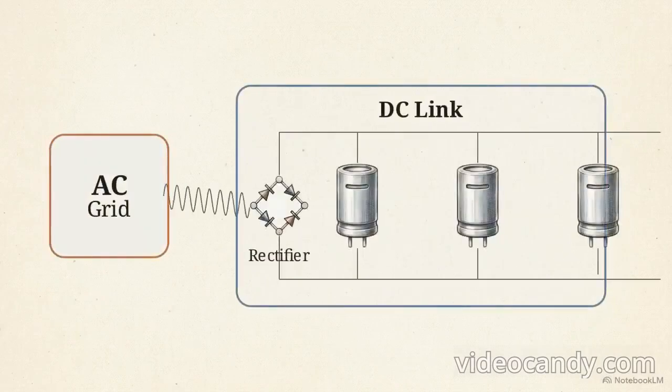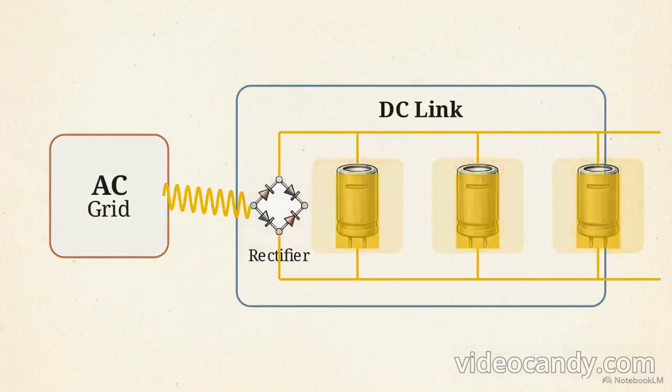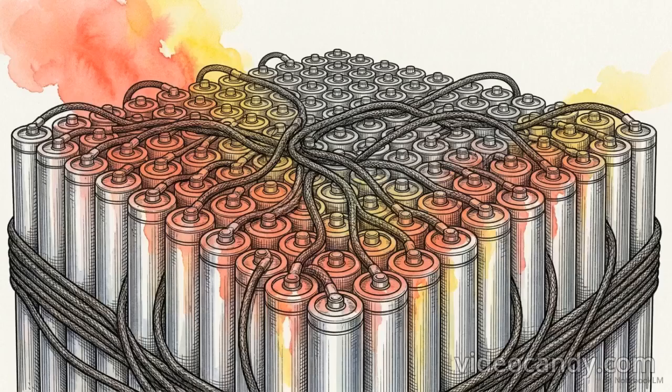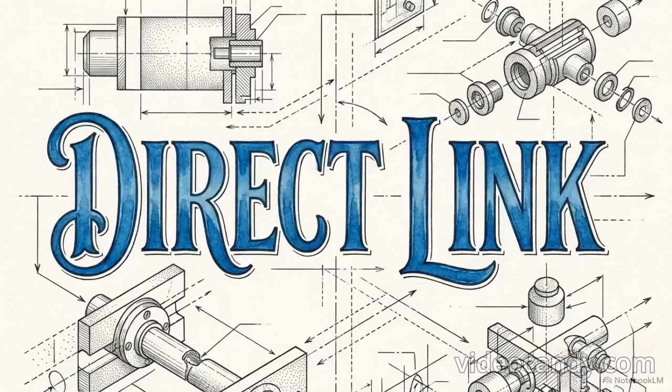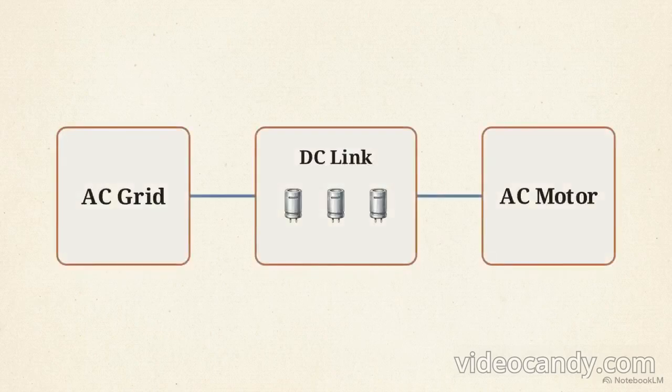The standard method for changing frequency is a multi-step process. Convert the grid's AC power into DC and store it in massive capacitor banks. It's then synthesized back into a new AC frequency. At megawatt power levels, those intermediate capacitors become dangerously large, causing heavy energy losses. Achieving true high power efficiency means cutting out the middleman entirely.